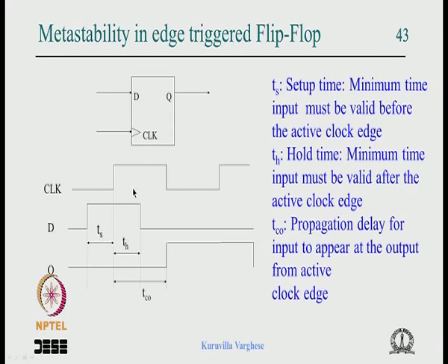Not only that, after the clock edge the data has to remain there for some time, and that time is called hold time. So unless the data at the input meets the setup and hold time, the Q will not get a copy of the value of D. The D will not be transferred to Q properly.